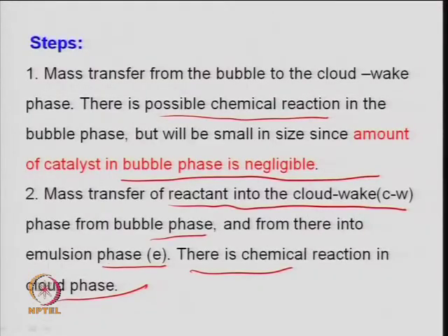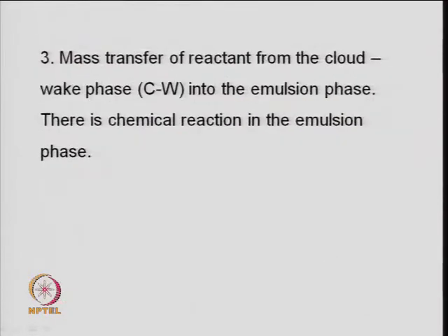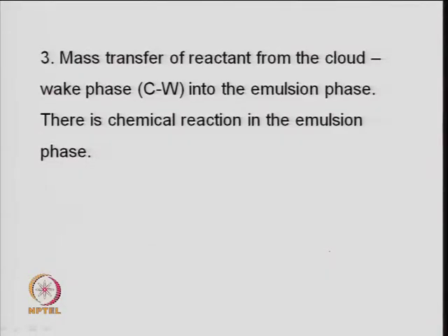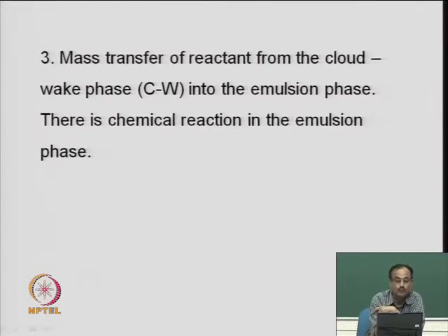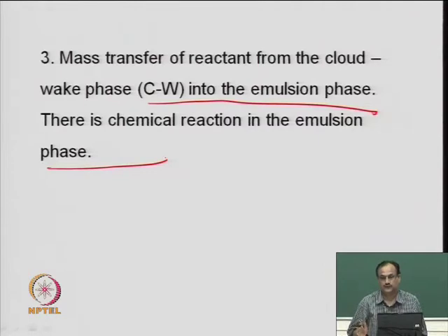So, this is your second step, where there is a transfer from the cloud and wake to the emulsion phase, and there is a chemical reaction. And then the third step, when it reaches the cloud and wake, there is no mass transfer, mainly it is a chemical reaction. So, that is basically in the emulsion phase, right. So, mass transfer of reactant from the cloud and wake phase to the emulsion phase, that we already talked about, and now there is a chemical reaction in the emulsion phase, and there is no further transfer, right.